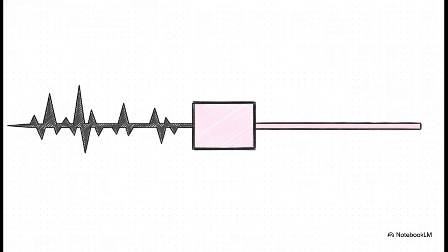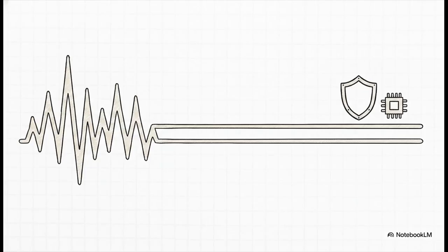When we analyze the inductor current, we see exactly what we'd expect. This continuous, jagged ripple waveform. That's just the chaotic, high-frequency noise of our pump charging and discharging 25,000 times a second. But thanks to our perfectly tuned 22.6 microfarad capacitor, that jagged energy is completely smoothed out at the output. The result? A flat, perfectly stable, beautiful line sitting exactly at 320 volts with negligible ripple. The filter works flawlessly. If we zoom out and look at the system over time, the simulation shows us something else that's super important.